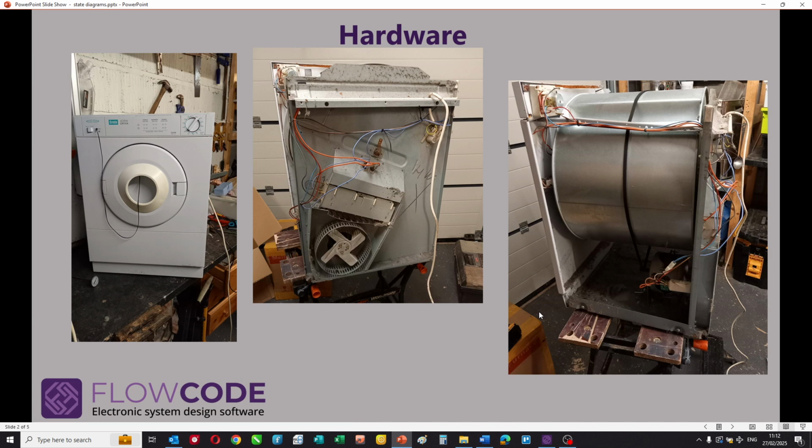So this is a malting machine that I made a few years ago. I started off with a tumble dryer that I bought on eBay for a tenner because it wasn't working. And when I took the back off, you can see there's the induction motor with a fan on it, and as often happens with induction motors, it was just a capacitor that had dried out and needed replacing. And once I'd replaced it, it was fine.